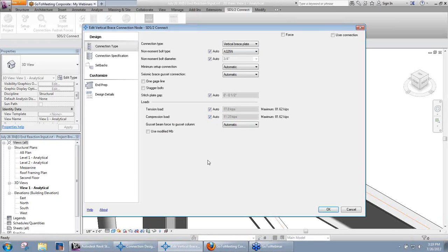You can also choose to do your automatic for your compression there if you need as well. Again, it would be the 50% or whatever percentage we had set up in those options that I just showed. Again, you get your maximum capacity for that set over here. If I increase that, we're going to do a redesign. Notice that maximum goes up as I do the redesign on it.